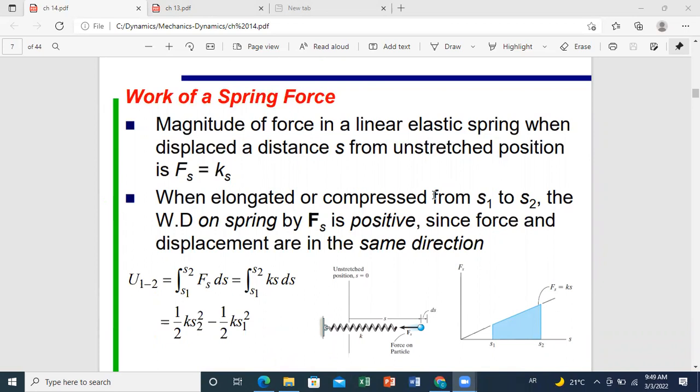If it's positive upward, then the expression of the work of your weight is minus W delta Y. Because look, if you have y-axis upward, this means that when you move up, the work should give you a negative result because the weight will oppose it. So the expression of the work of the weight when y is upward is minus W delta Y.